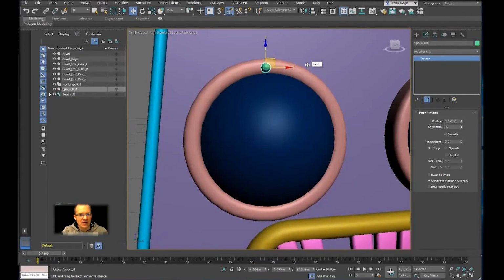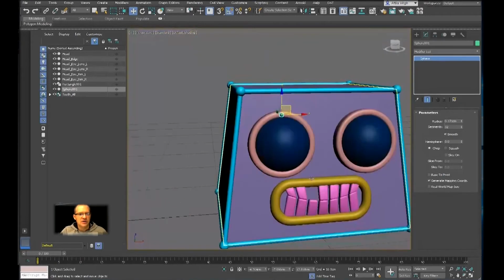This is called array. Array can populate items in a specific and accurate manner. Here, this was mostly guesswork. We were eyeballing, checking out the distances and the sizes. But right now, we'll do it a little bit differently, by values and not just drag actions.